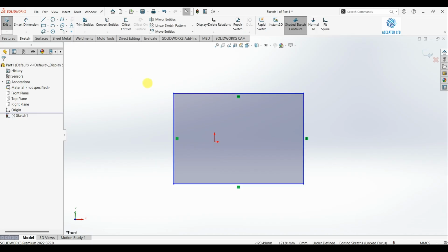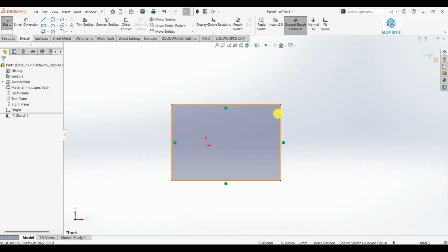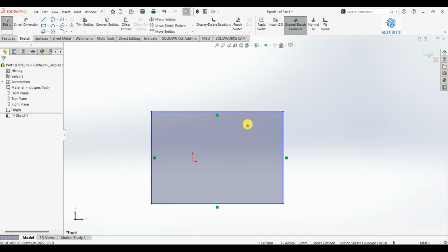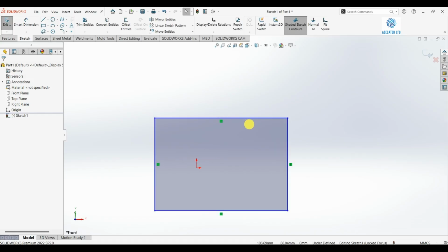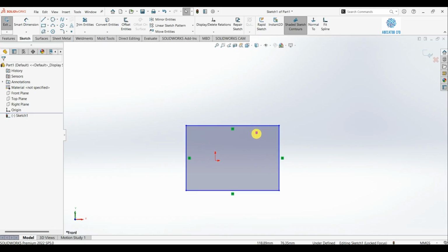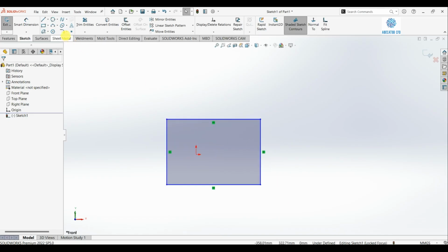Watch the yellow preview. Adjust it until smooth. Undo if needed. Very common in practice. First, what are these tools for? In many real parts, we often need them. We want to remove sharp and cutting corners, so the part is safer to handle. We do that by rounding or beveling the corner using fillet or chamfer.